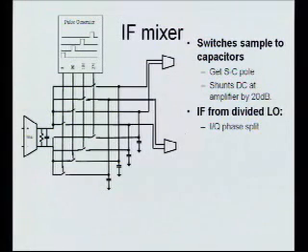So you divide your LO down a fair ways, down to sort of the right frequency, and then when you divide, you just notice, for example, basically you have, say, a modulo 8 counter. So it has 8 possible states. And for each one of those possible states, you turn on one of these switches. So it just changes configuration, turns on different sets of switches. And so some of those switches turn on at the beginning, some turn on a quarter of the way through, that's 90 degrees. Another one turns on halfway through, that's 180 degrees, and then the last one at 270. And now you've gotten quadrature for free.